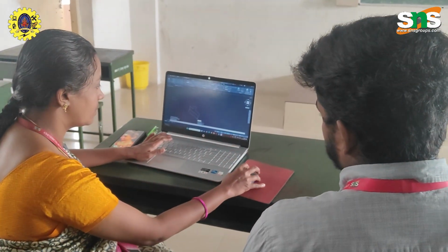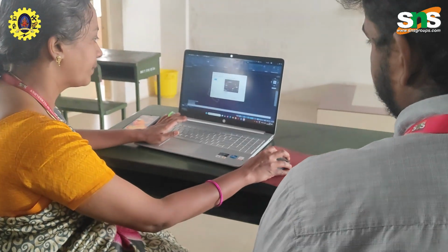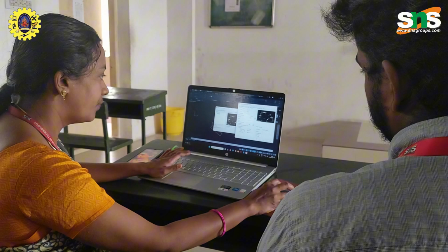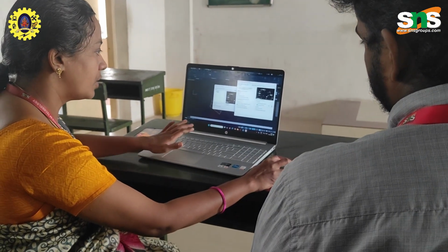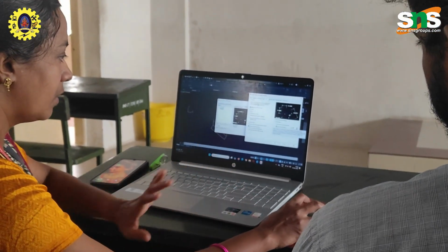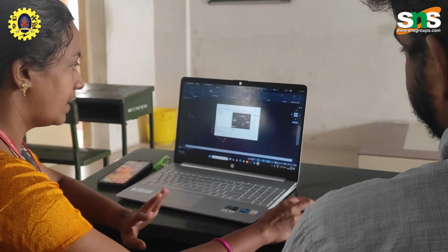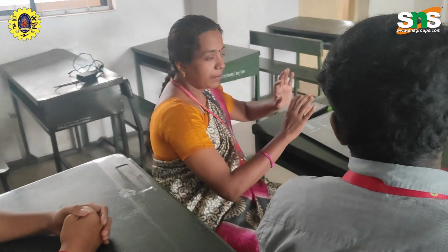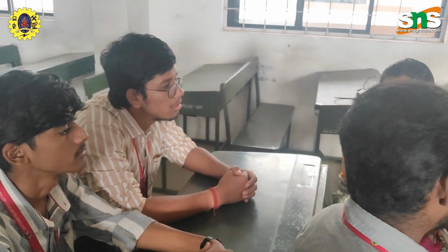So I go to dimension style, modify, fit, and I change it to 10. Okay, set current, and then close. I am giving all the options and refreshing it with set current, and I got the value.